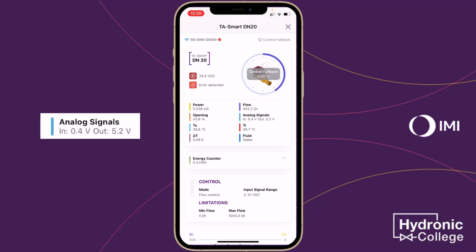Once normal input signal has been retained, the fallback position will stop. As you can see, we are now receiving an input voltage of 4 volts and the valve setting is being controlled via the input signal once more.